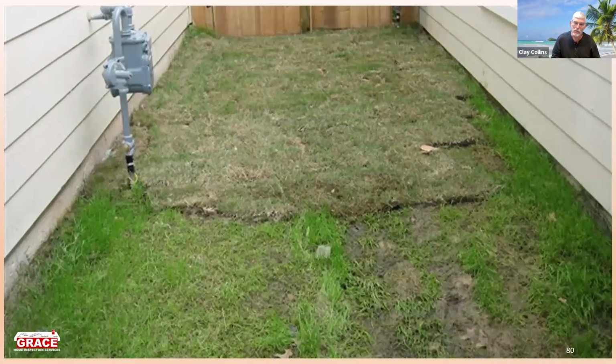We had a pretty good drainage swale. So somebody was upset with that low, muddy spot. So how long before they start experiencing flooding towards the back of the property? How much time before they start experiencing foundation movement? Remember, 10% expansion on the expansive soils. And they have created a condition here that will promote that 10% expansion.